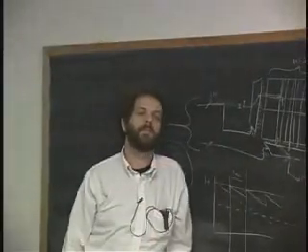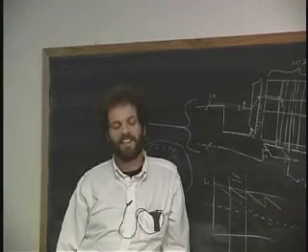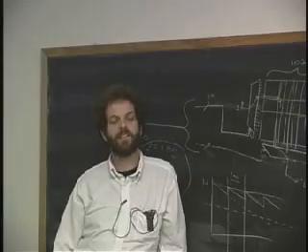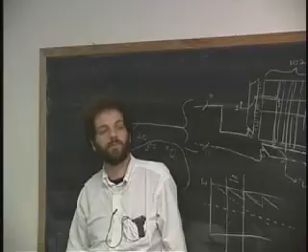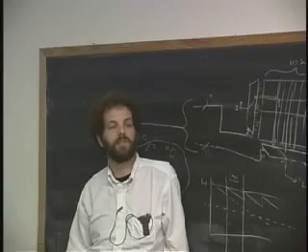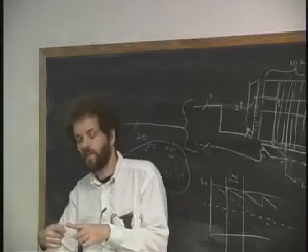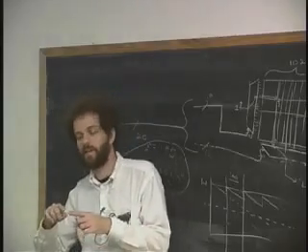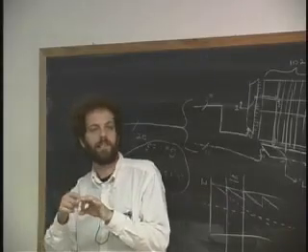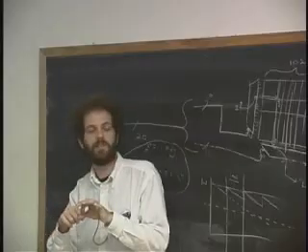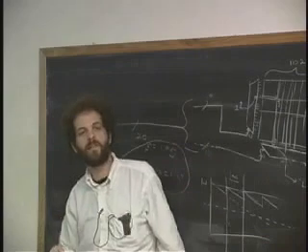Besides capacitors? That's really a great question. There have been a zillion different ways. A lot of them use magnetism of one form or the other. In the old days, of course, there was core memory. And so you had wires that crossed, and when you put a current through a wire, you get a magnetic field that goes around the wire. And you can have a ferrite core, and you can magnetize it either one way or the other way. And then you can send another wire through and tell whether or not it was set one way or the other way. So that's been done.